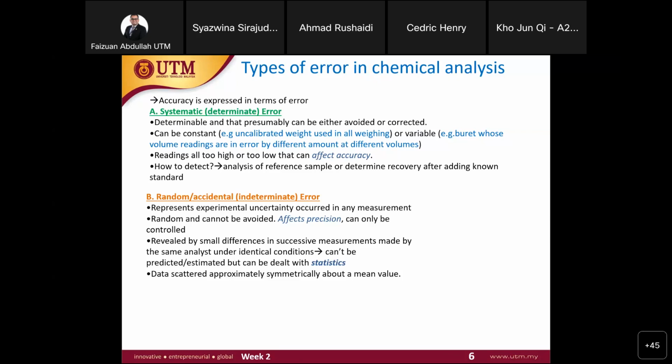Okay. So the acceptable value, please take note. Guys, please take note. The acceptable value for the recovery is plus minus 20%. Meaning that, in the example again, 10 ppm of mercury, if we analyze and get 12 ppm or 8 ppm, it is in the acceptable range. Why? Because the acceptable value is plus minus 20%. If it is 20% low from the actual value, it is acceptable, and if it is 20% high from the exact value, it is also acceptable. More than that is not accepted.